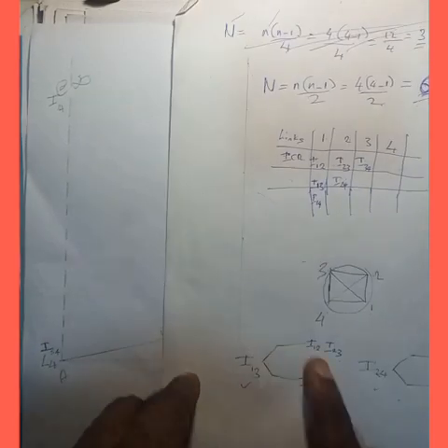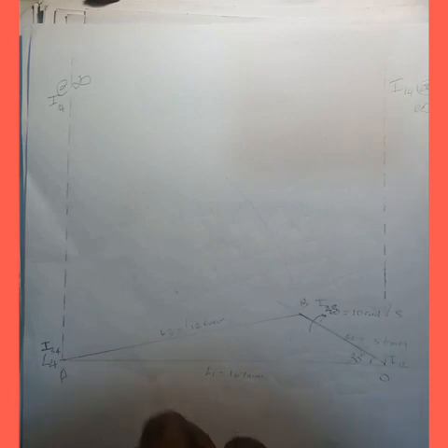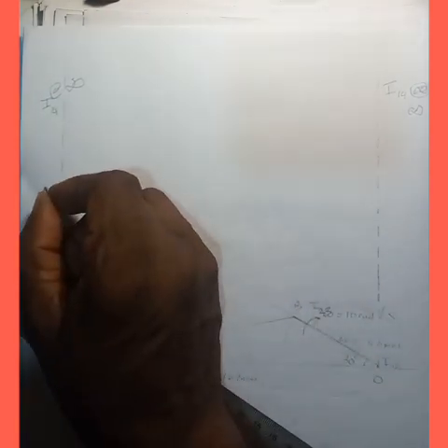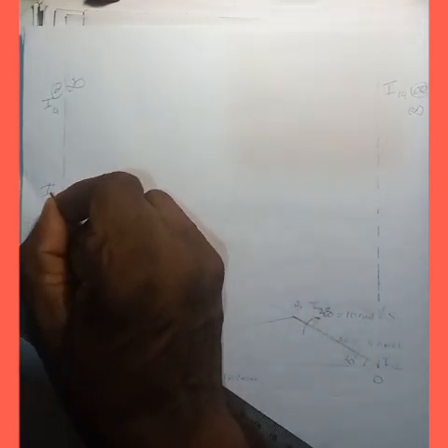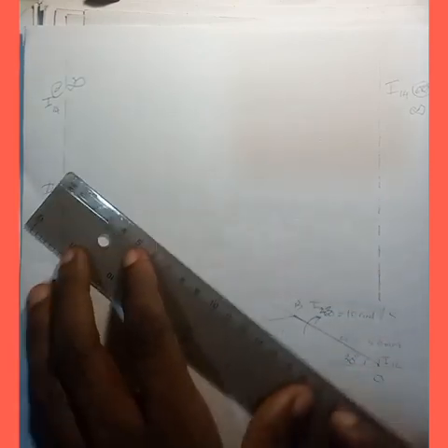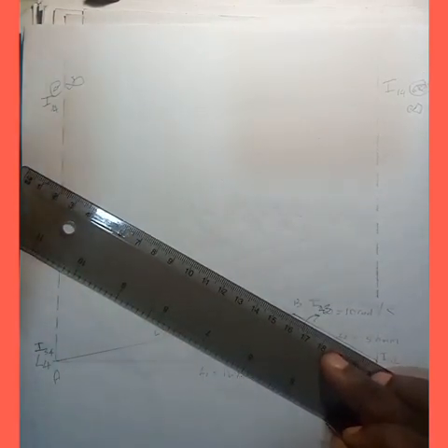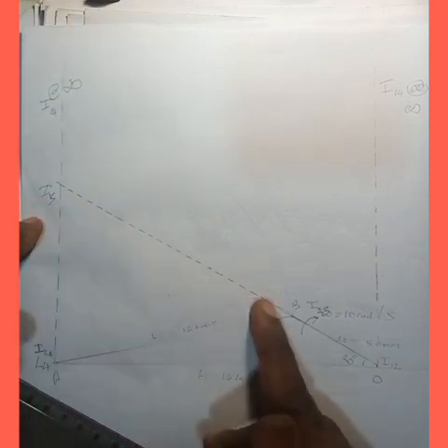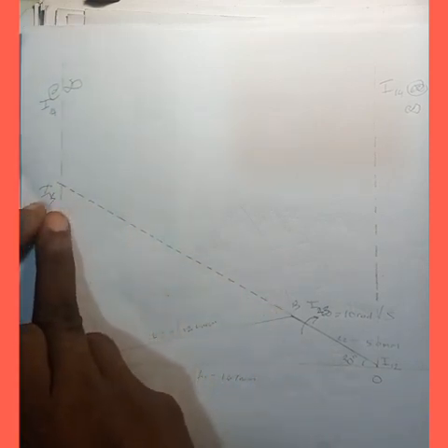So all you need to do is take your line, you draw a straight line that will intersect here. So wherever it intersects, it's going to give you your I13. So first, let's draw it and get the intersection. So now this is your I13. So with this, using a short dash line, you'll be able to locate our I13.